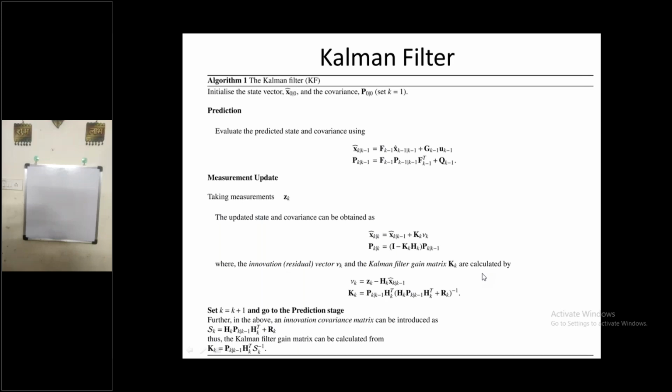Okay, then we have to add this Kalman filter to some other algorithms, like how do we reject a noisy sensor or something like that? Yesterday I told you about fault detection. If you're using redundant sensors, suppose even if you use 3 sensors from the same manufacturer of the same quality, one sensor can be faulty and the other 2 sensors can be working fine.